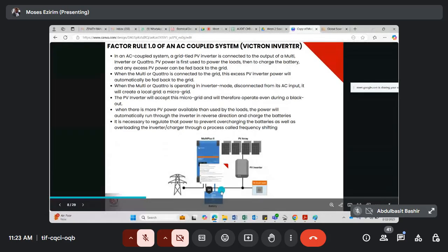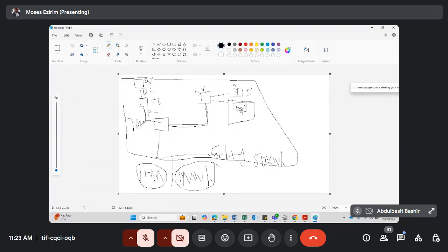So now, if you don't factor that, let me assume that my PV is generating 70, all right, and what the facility can take is 10 kilowatts. What will happen? The remaining 60 will pass through my output down to charge the battery. Now, that can actually overload the battery, all right, and because it can overload the battery, your battery inverter will not want that, and since it doesn't want that, it will be shutting down. Don't worry, let's move on so that you understand better.